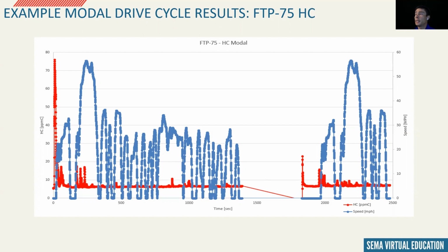If we have high spikes in this area where we feel the results are impacting our hydrocarbon emissions, we should first look at transient fuel control. We need to make sure that we are not too rich during tip ins and tip outs. If transients are good, we should try to control our dithering, spend more time lean, for example.